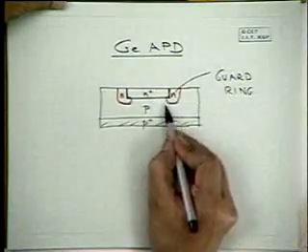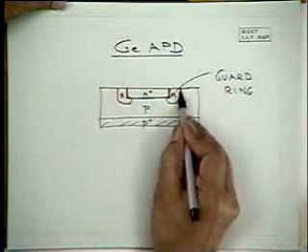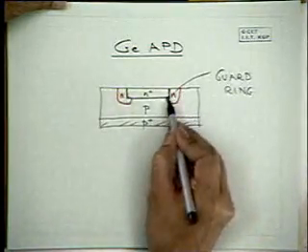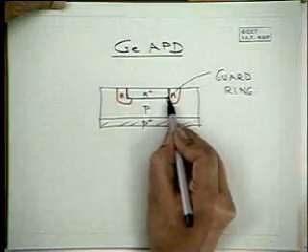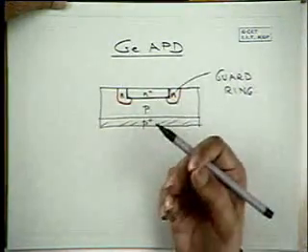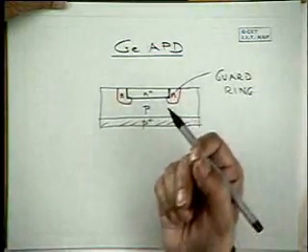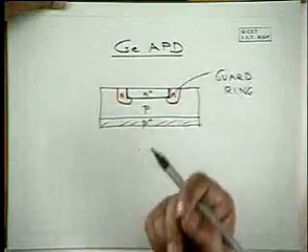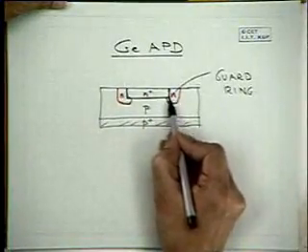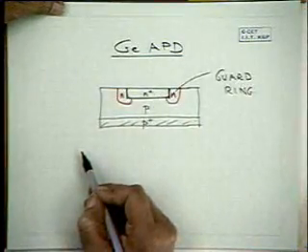So the electric field at this corner is spread out over a larger region, so the electric field does not become too high, and breakdown does not occur at this corner. It's like a lightning rod. Why is a lightning rod good for arresting lightning? Because it's very sharp, the curvature is very high, so the breakdown field is very high. So this is trying to reduce the curvature and raise the breakdown field.